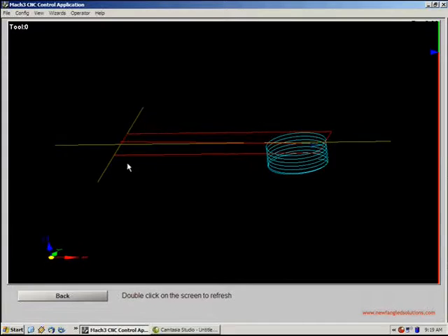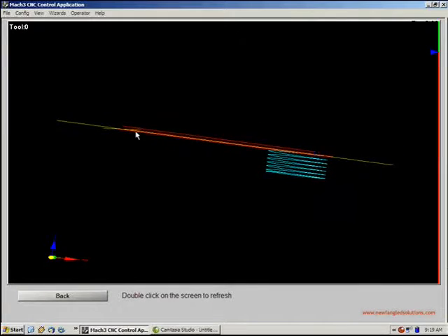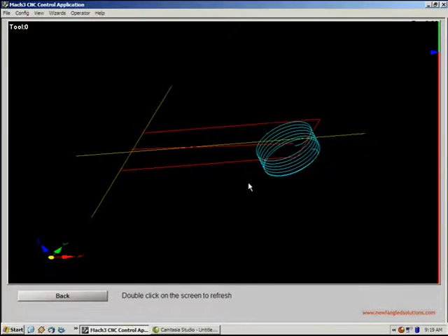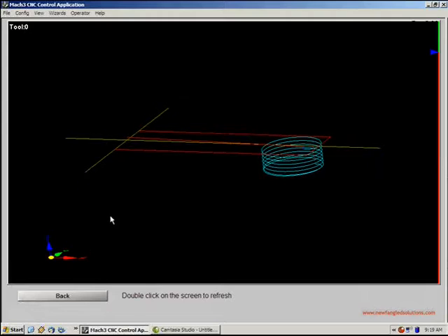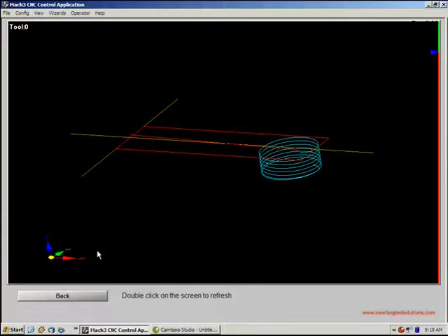Get that so we can see it real well. So just like that, we have a helix that comes down. It comes in and just helixes down, and it does a pass along the bottom, all the way around the bottom of the pocket. This is a very nice finishing pass and works well in softer materials and harder materials. It's just all around a little bit better. It's kind of fun to watch in comparison to the other one. Another benefit is it only gives you one compensation number that you need to adjust when it goes into the pass.